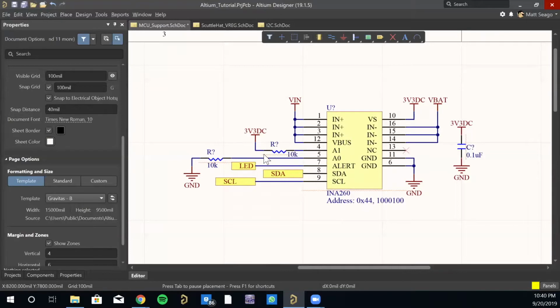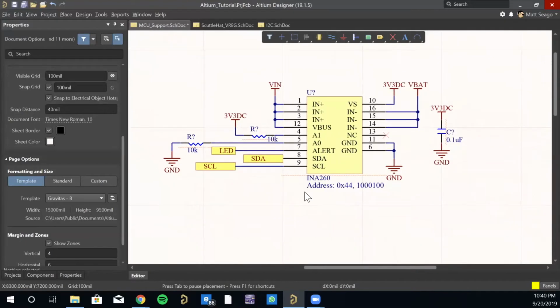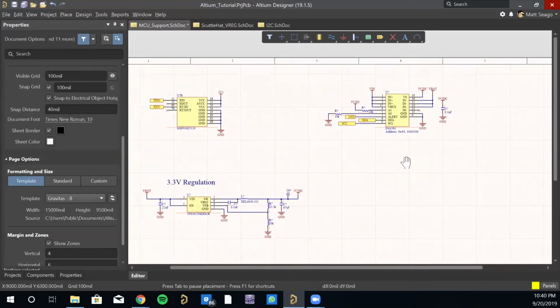These two A's are setting the address of the device per the device's data sheet. So you could have probably 4 of these, and they could all have different addresses and not interrupt each other if that was something you needed.